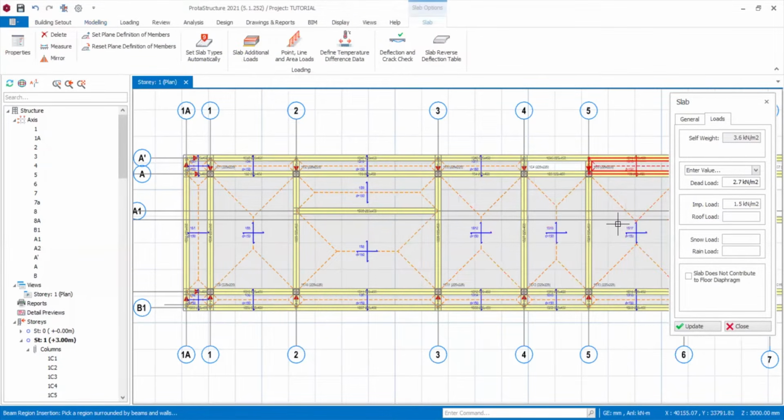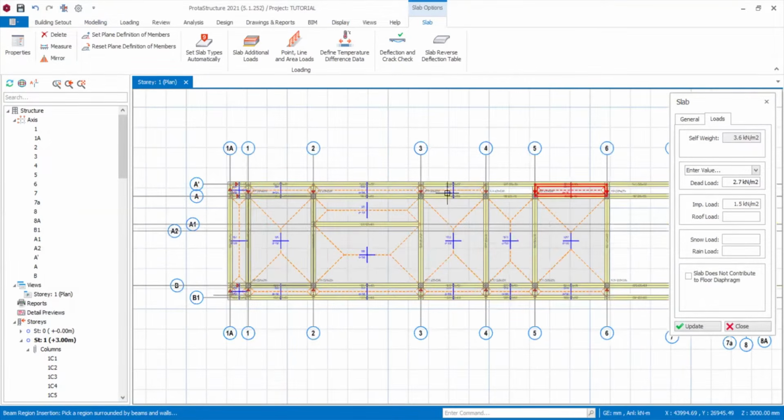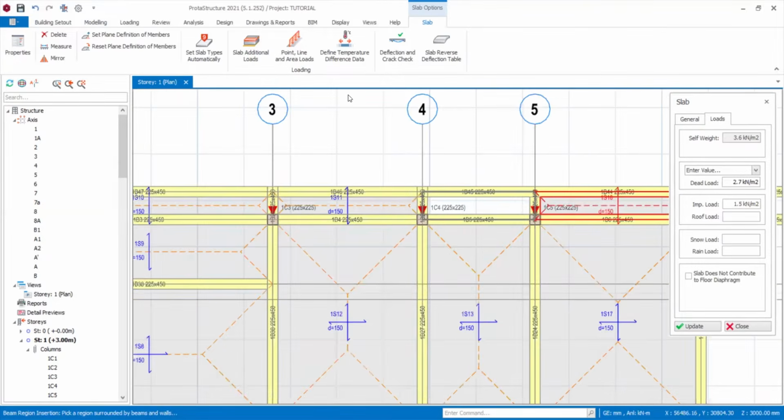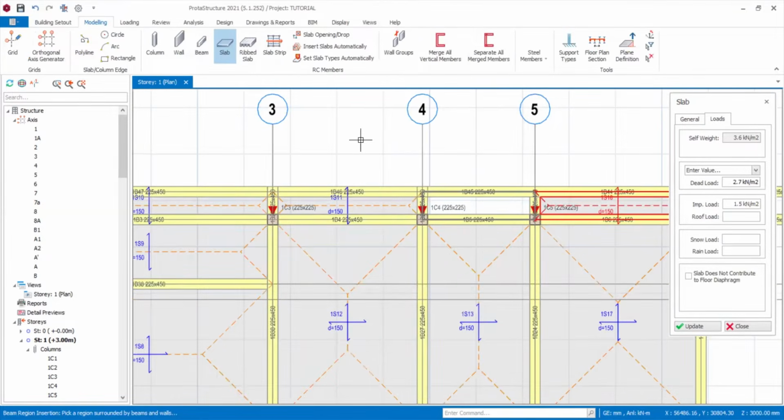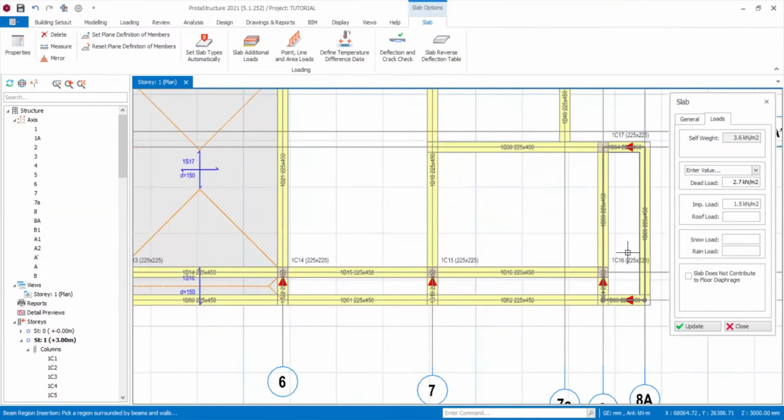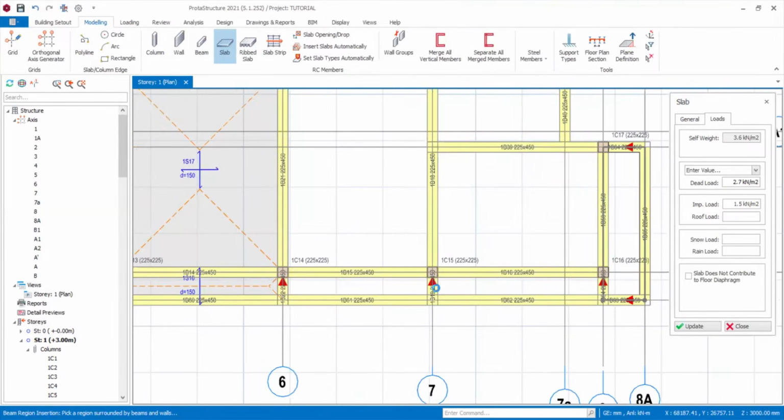Because the reason for my cantilever beam is because all these columns you are seeing presently, majority of them are stopping at this floor, not going to the roof. And I want to support my roof beams. So I'm trying to devise a means around that. That's why I'm using this option. So if there's a way of going around that without this, why not? It's free.